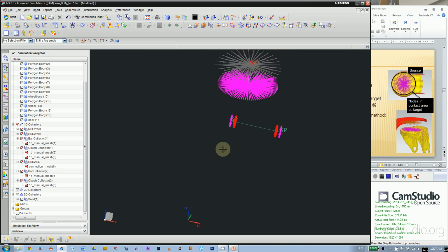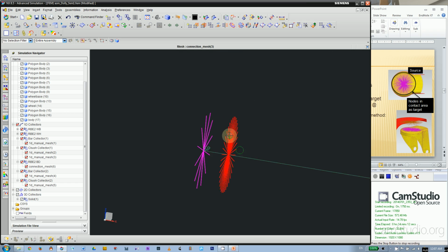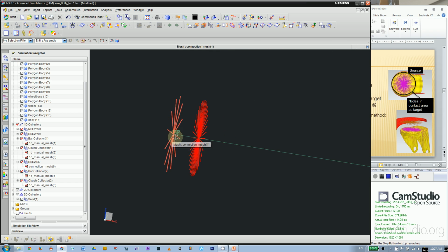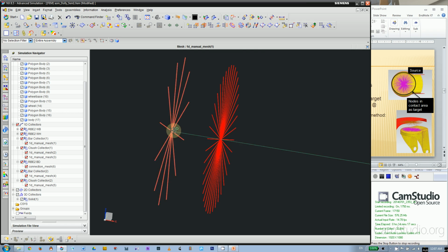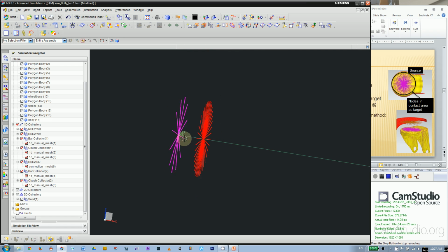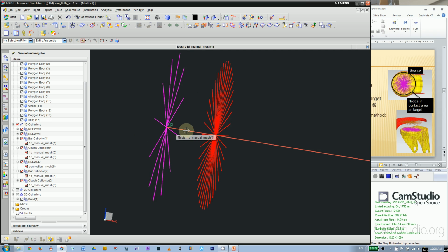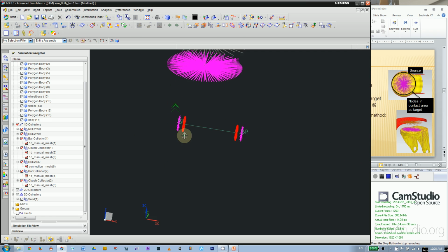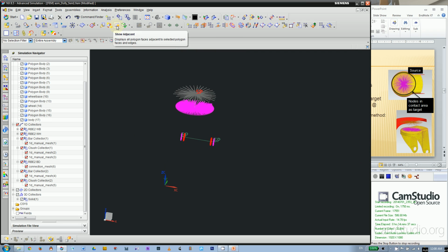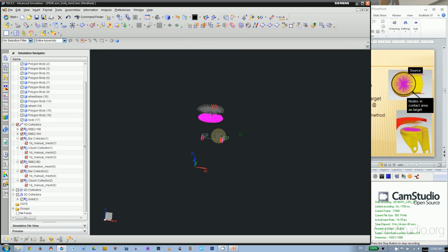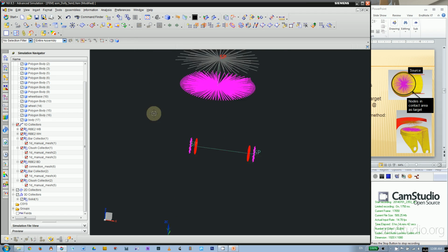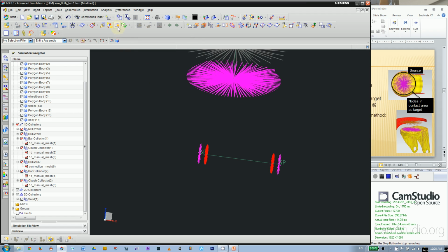Usually it's the connections. It's quite confusing at this spot that you have coincident nodes. You have a bushing between the spider and the beam. How do you know the spider is actually not connected to the beam? How do you know that there is a bushing between them? We have a tool called show adjacent. It will show whatever element is directly connected to your selection.